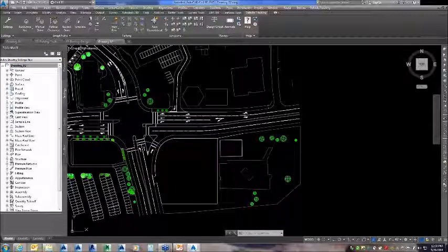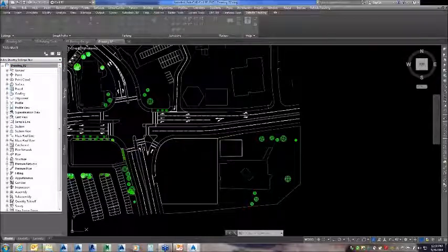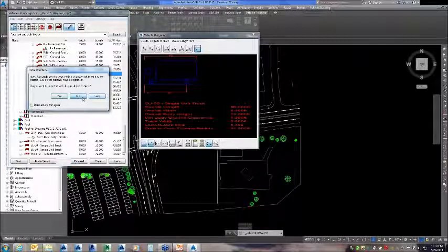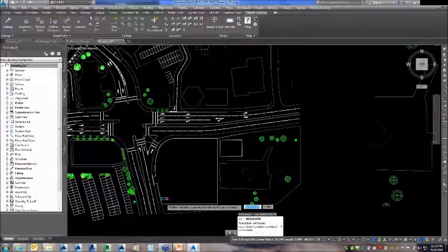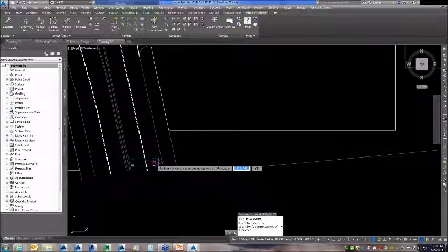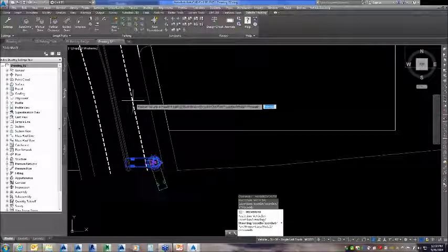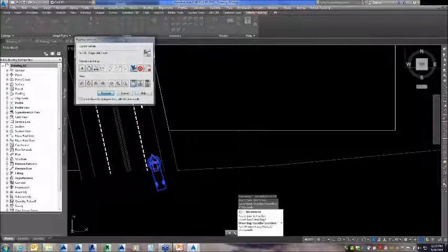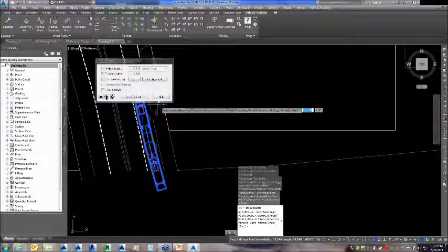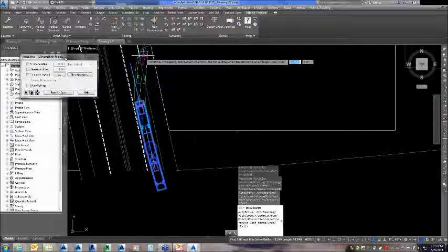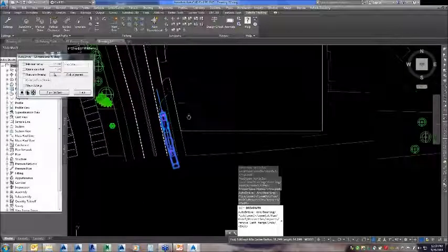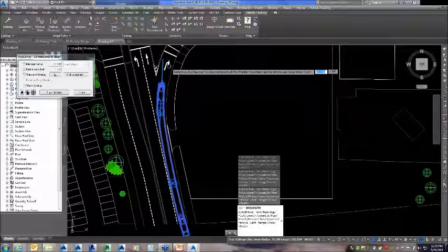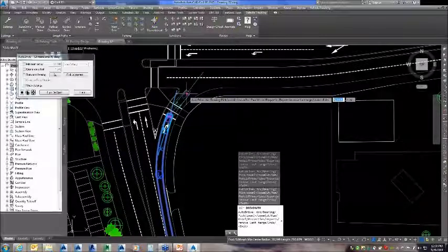Now let's just take a look here. I'm going to select my AutoDrive. The same vehicle is going to be fine. I'm not going to make it a default. I'm going to drive right through here. I'm going to pick on this point. I'm going to select proceed. I'm going to pick that point. I'm going to just move this over here just a little bit. I'm going to come in here, just pick here. So something pretty straightforward. Whether it can make that turn.